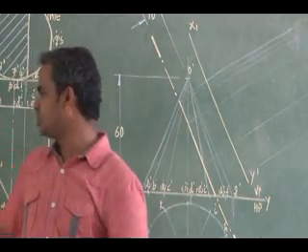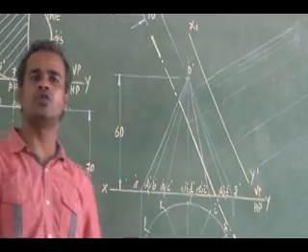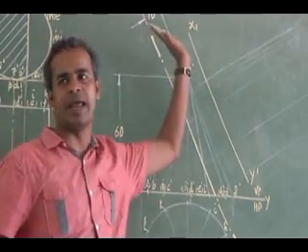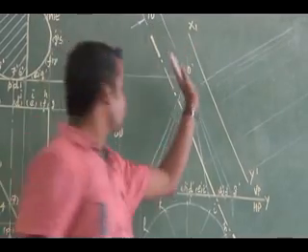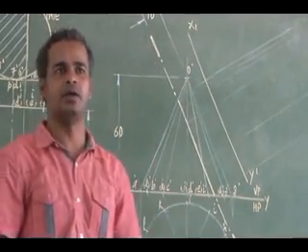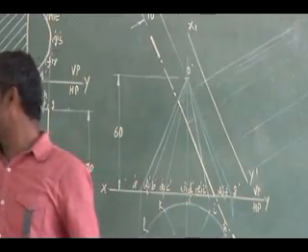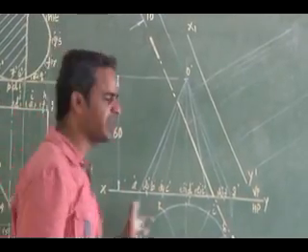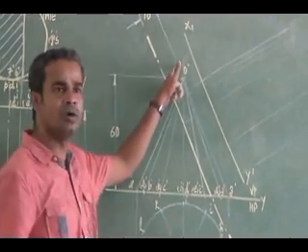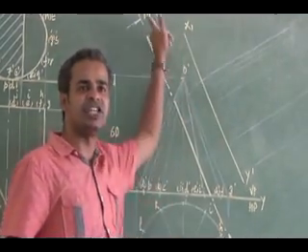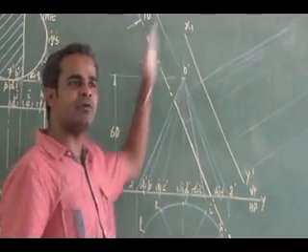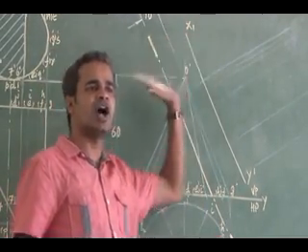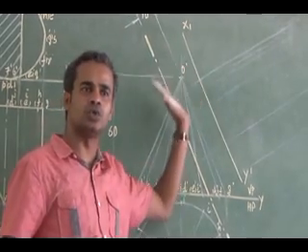Cutting plane position is given, it is perpendicular to VP. So where I have to represent on VP, I have to represent the cutting plane. Right. So in front view, I have to represent the cutting plane. Then it is parallel to one of its extreme generators. Which is extreme generator? Here I have AO and GO. So either parallel to AO or parallel to GO, I can draw a cutting plane parallel to that at